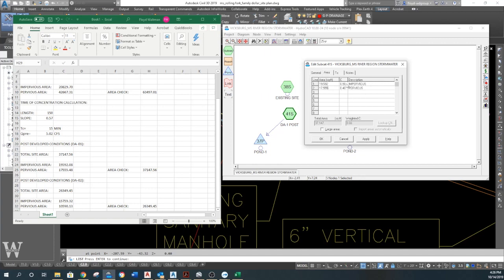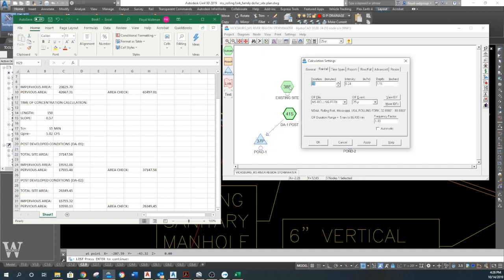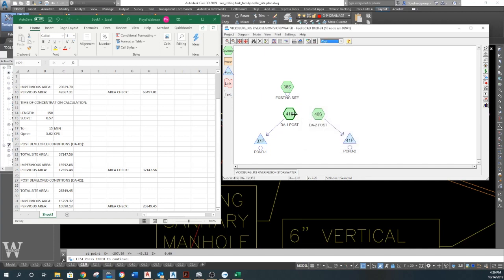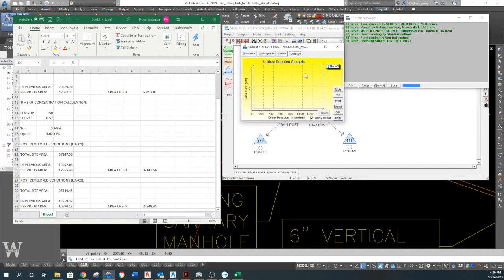Okay, I use the same 0.9 and 0.4 for asphalt. Those are numbers that are standard for stormwater design for coefficients in the rational method. You can go look those up if you need to check those. Time of concentration, this is a direct entry method. We just tell them it's five minutes. Now I can go back in here and set that 5 minutes right here. It gets the intensity set, so I can look at that and find the flow. And if you want to double check that we did the duration right, we'll just double check it so you can see that 5 minutes does work.